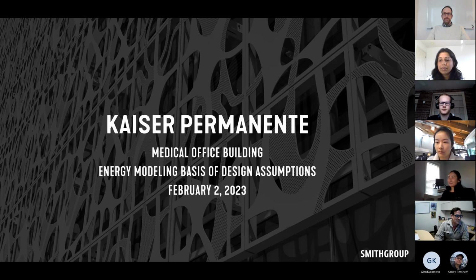For as long as the ASHRAE handbook has existed, mechanical engineers have been doing load calculations. We do cooling load calculations, heating load calculations, and then more recently, in the last 30 years, annual energy calculations. Unfortunately, in the US, it is not common practice to validate those calculations. Most of the time that an engineer does a peak cooling calculation for a building, it gets built and then put into service, and there's no real concerted numeric effort to go back and check those calculations against the peaks that actually occurred in the building. And that's similar for heating loads and in most cases for energy calculations as well.